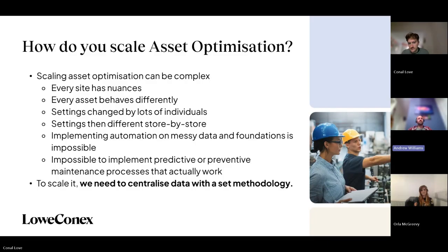Once you've done that, you also need an effective way to send commands to your BMS solutions. You can sometimes do this on the BMS platforms itself. So if you take RDM as an example, you have a TDB editor. You can create a bespoke TDB program, which can be implemented on a BMS by BMS basis. Really, it's not scalable. What you want is a cloud-based solution where you can create these rules in a platform, and these rules can then be diverted to all the different BMS solutions that you're going to come across. So it comes down to having a centralized location that allows you to control and monitor from a single location.